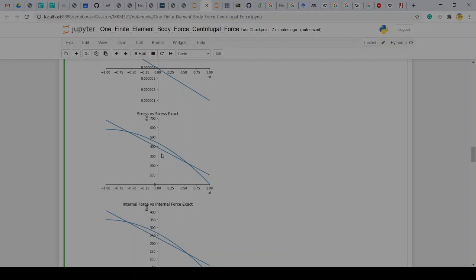And so this is what the approximation is doing. At that right-hand edge, at the edge of that bar, if you were to put a stress sensor with a normal pointing upward, you would expect to see 0 traction. There's no traction applied there, and there are no body forces beyond that pulling on that part of the material. But what we see is that in the approximation there is a non-zero stress at that edge.